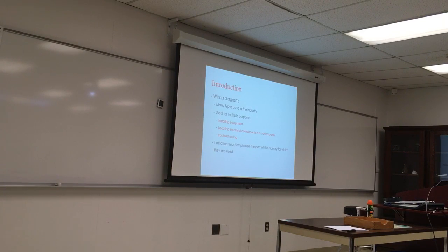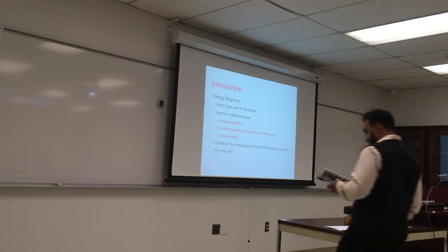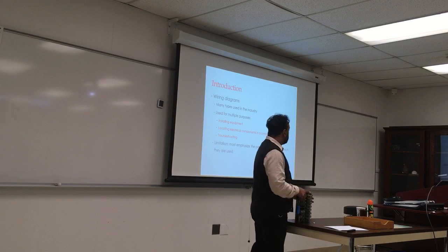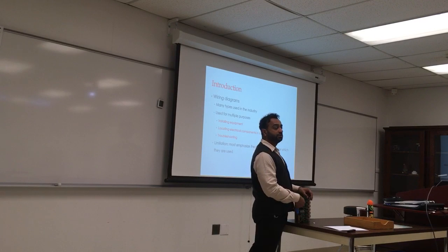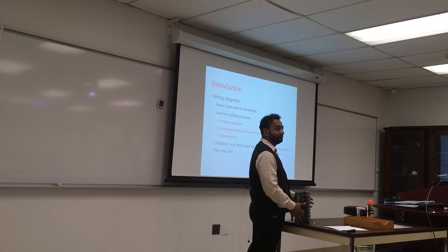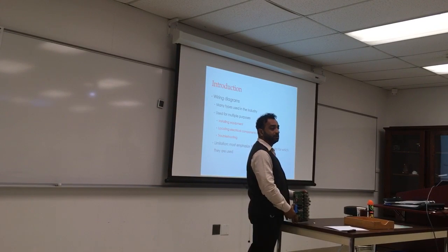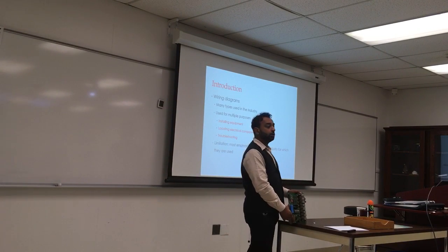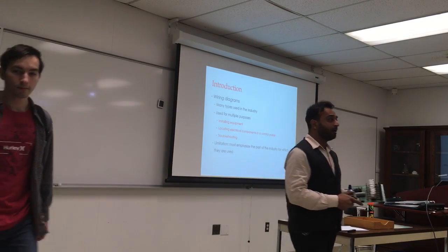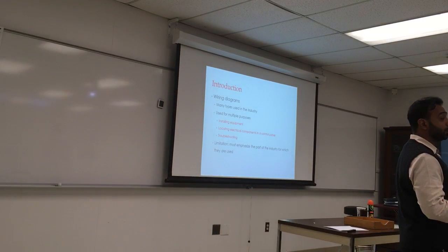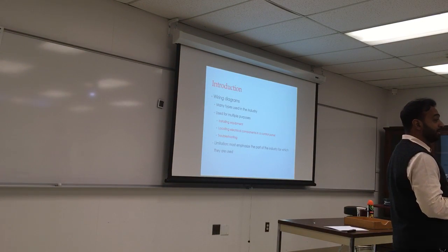So this is a switching board. And you can also have a zone valve switching board. If you have a house that has 3 zones, the first floor, second floor, garage, you need something to determine which one receives heat or not. So you're gonna have some kind of a switching board. And it's your job to wire that switching board. And to do so, you have to follow the right instruction. And most control equipment are how many volts? Control, 24. And equipment are 110.